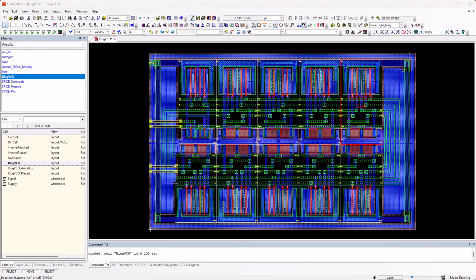Design changes rarely happen around an object center as well. More often designers need to keep a specific edge, rail, or feature fixed while transforming geometry. Basepoint enables rotation around any chosen reference location. By rotating around a selected rail edge, the transformation follows the designer's intent rather than an arbitrary origin.